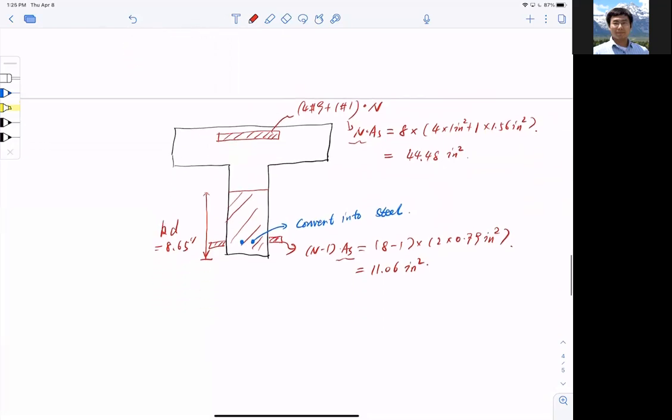Okay, so now if I call this 1 and this is 2 and this is 3, I can compute my ICR negative. And again, let me quickly skip through this process. And I got this number, and sorry, let me use a different color here. I have gotten this number from my calculation. That is ICR negative, 11366 inch to the power of 4. And this is obtained miraculously, right? Without any detail, any process, I just got it. Okay, ICR equal to 11366 inch 4.